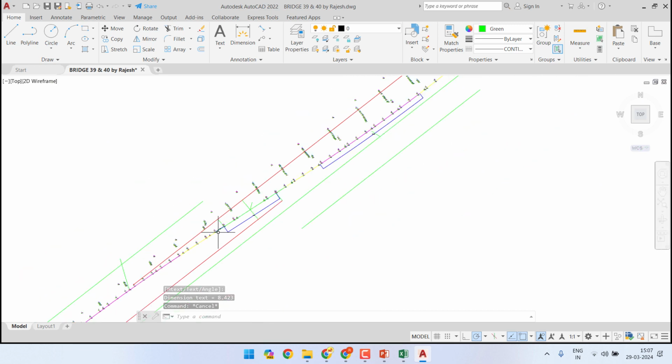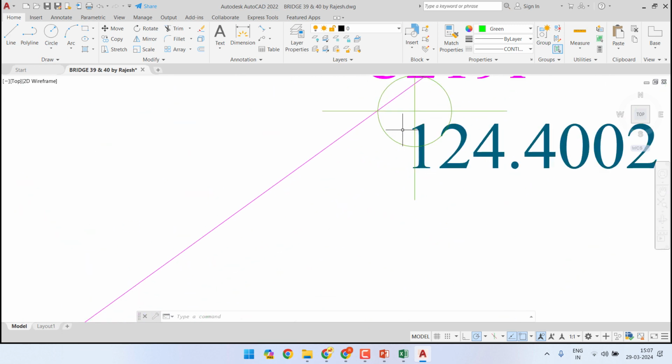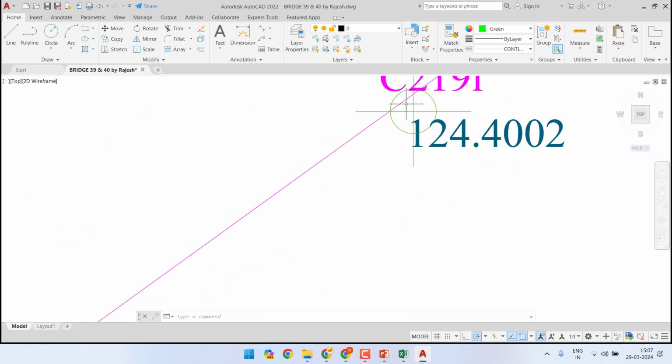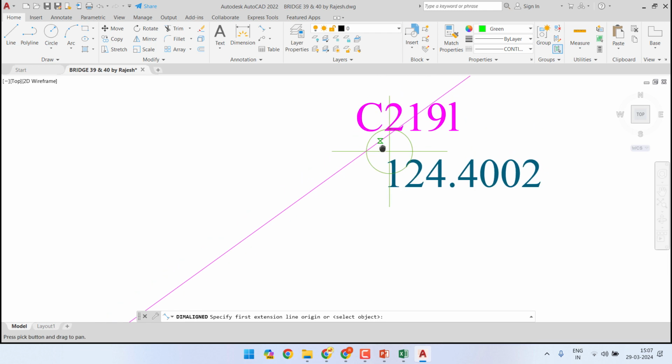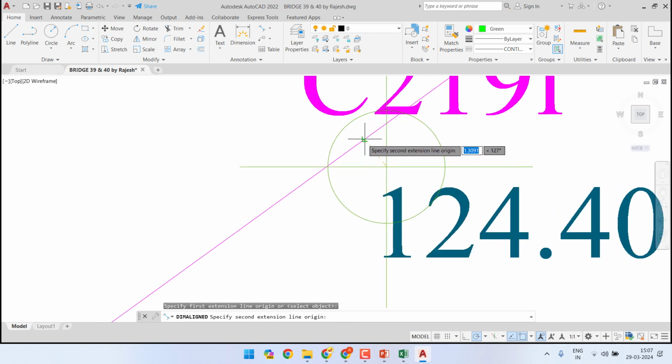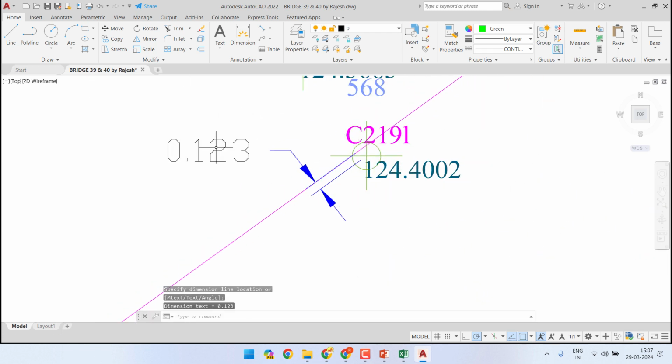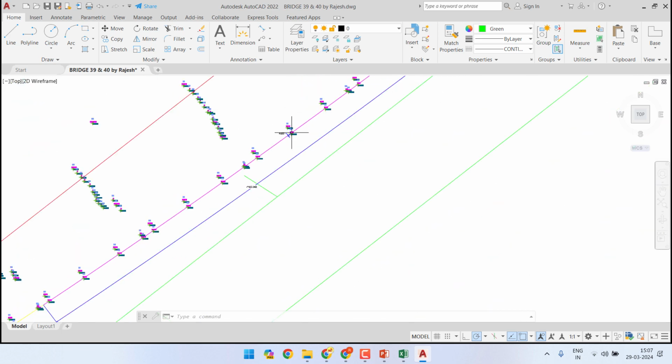For the purpose of our work, we can use this data as the actual or correct data, and every offset that we get here like this will give us the desired slew value. Like here we get 123 mm. We need to slew the track to the right side, which is going away from the OHE masts, which is acceptable as a matter of fact.